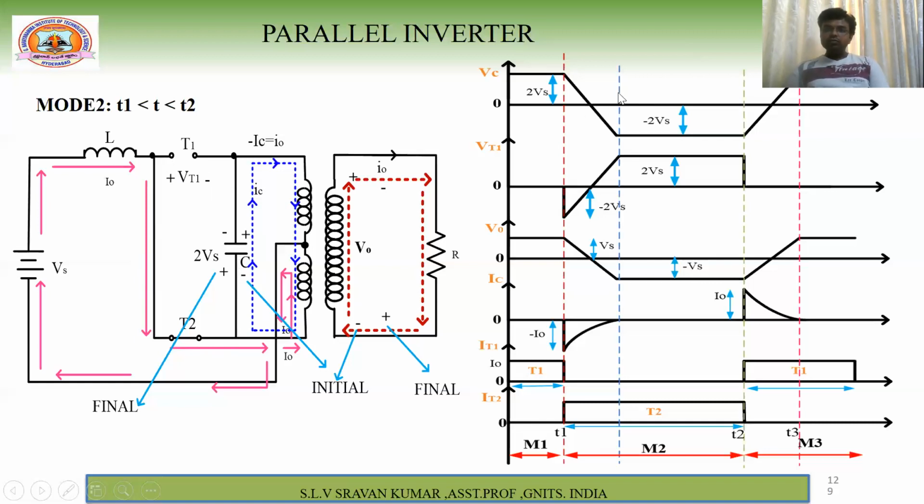Next here, negative. When you are having negative voltage, that means these polarities are coming into the picture. Negative is applied to cathode, positive is applied to anode. So these polarities are the same as your reference polarities. That's why you are getting it like this. Once it reaches constant voltage, your capacitor voltage across SC is also the same. Whatever this magnitude is, you will get like that.